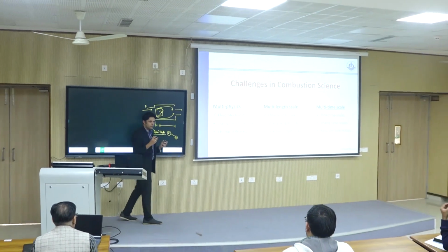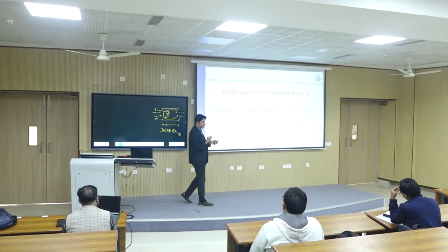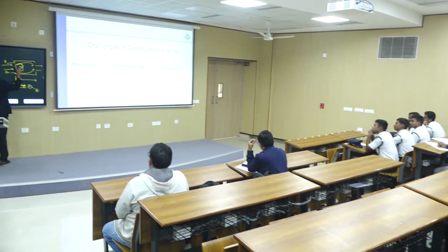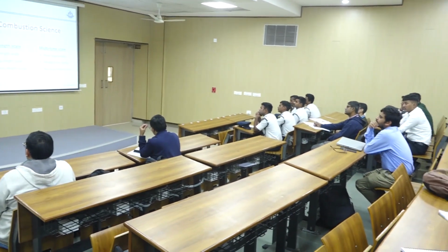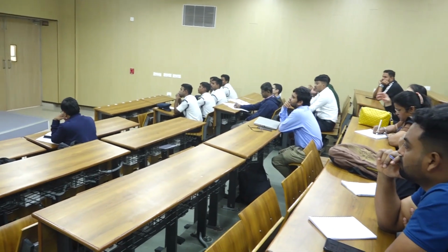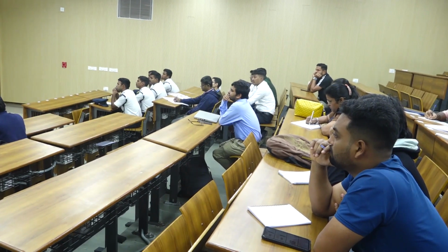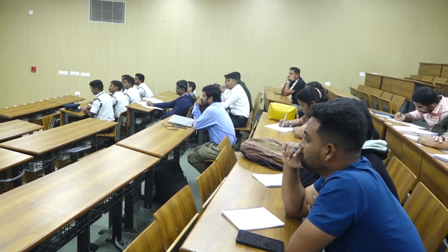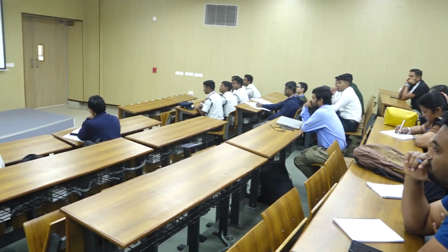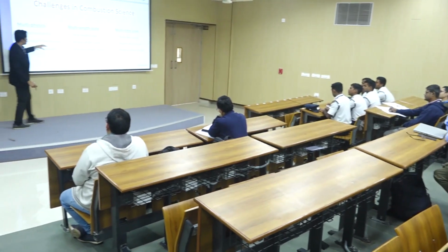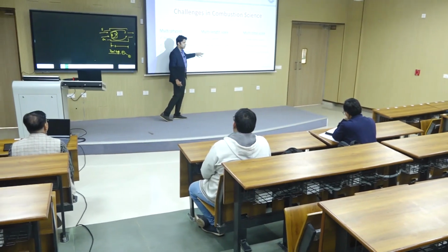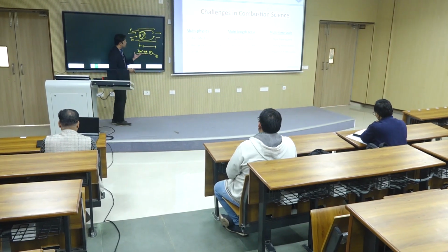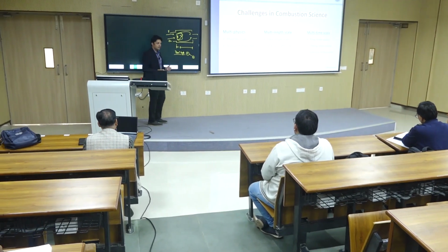The molecules of fuel and oxidizer are colliding with each other, and that takes place at molecular length scales. Those are way smaller than the mixing length scale and the flow length scales. So when you are trying to build a CFD model or resolve these governing equations, you have to look at these different length scales and handle them simultaneously, to simulate your combustion process accurately.